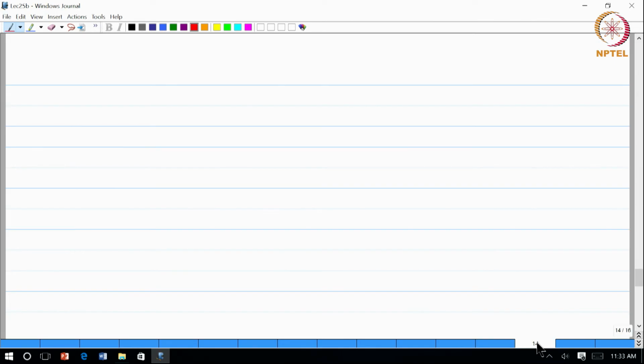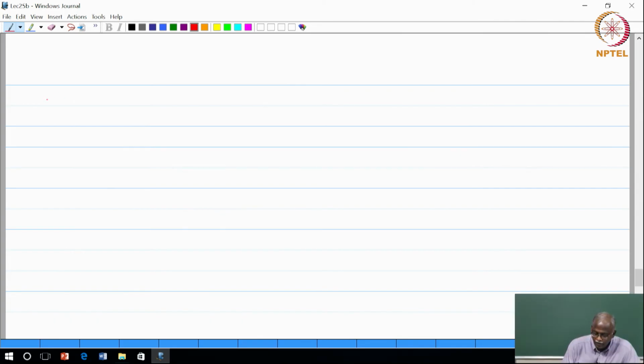So here is the way we would look at it. I will have an input, there is that crisscross form, I am just going to label this as k subscript n, and the delay is outside. What is inside is only the crisscross portion. The transfer function of this would be Gn minus 1, but now I am going to replace it with another lattice structure or crisscross, which is Kn minus 1.